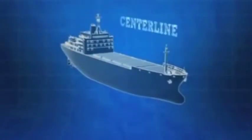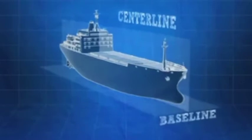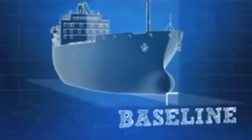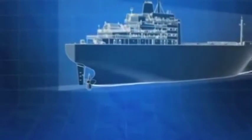The center line is a vertical plane that runs the length of the ship at the midpoint of its beam, and the baseline is a horizontal plane perpendicular to the center line, located at the lowest point of the hull. The keel is the principal structural member of a ship, running lengthwise along the center line from bow to stern, to which the ship's frames are attached.